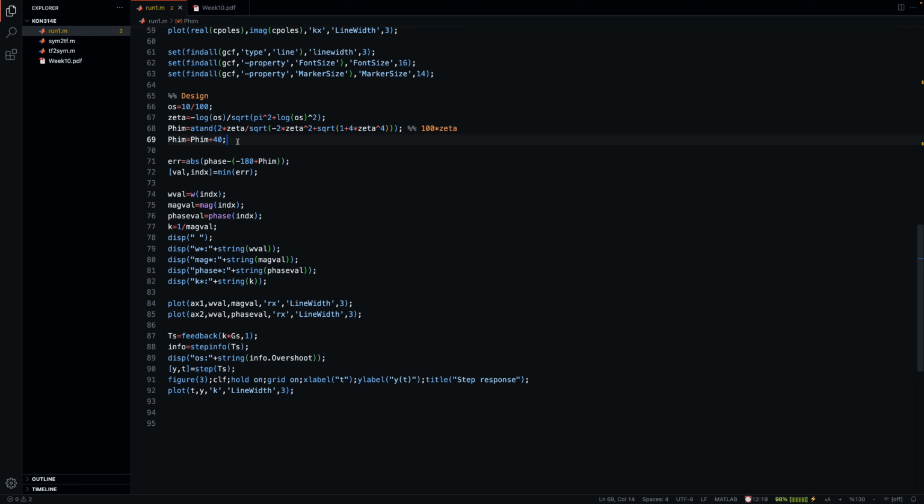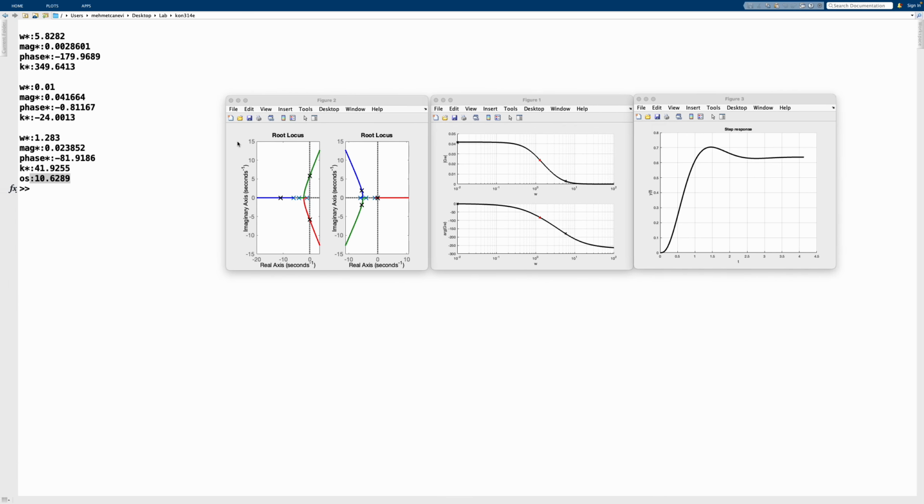Now, of course, you could also say, well, I have a p-type controller, I can just try the gains, and that's basically it. But you can see that this is not quite the same here, because we're using the Bode plot. It doesn't really matter what the system is. You can just use the Bode plot of that system, and we don't look at the transfer function, the model, at all. We just look at the Bode plot.